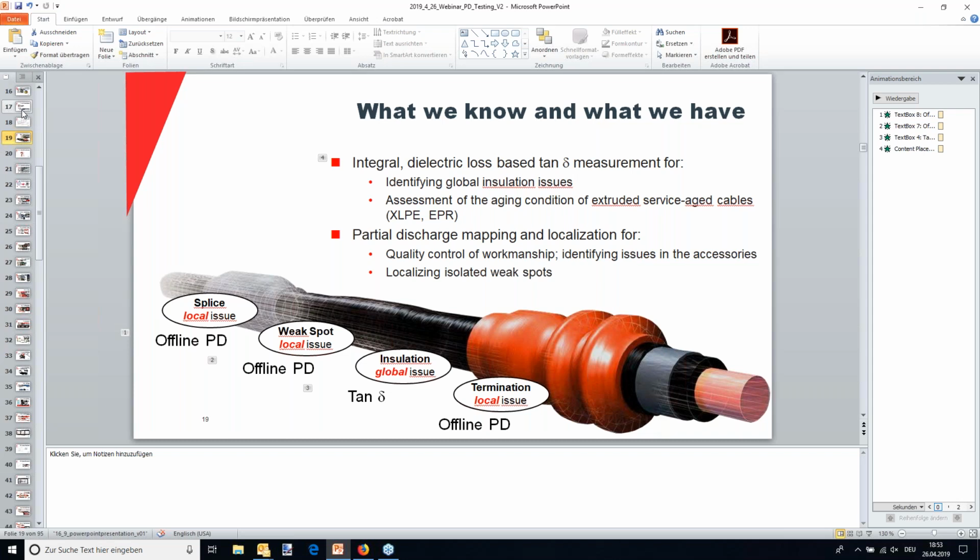The UHF uses a UHF antenna or radio frequency, and that is a spectrum analyzer really. And that is for the higher voltage environments, high voltage substations and end terminations and all of these things. So there's a distinct application difference, PD scan for medium voltage switchgear, and the UHF, as we call it, or the method is called UHF detection, that is for your substations and transmission substations.